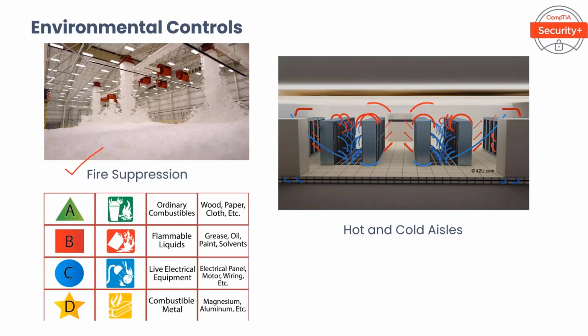So as you may know, fire suppression systems are rated according to class. First one is class A, right? So for class A fires like trash, wood, and paper, water decreases the fire's temperature and extinguishes its flames. Next is the class B. For class B fires, foam extinguishes flames fueled by flammable liquids, gases, and greases. Liquid foam mixes with air while passing through the hose.